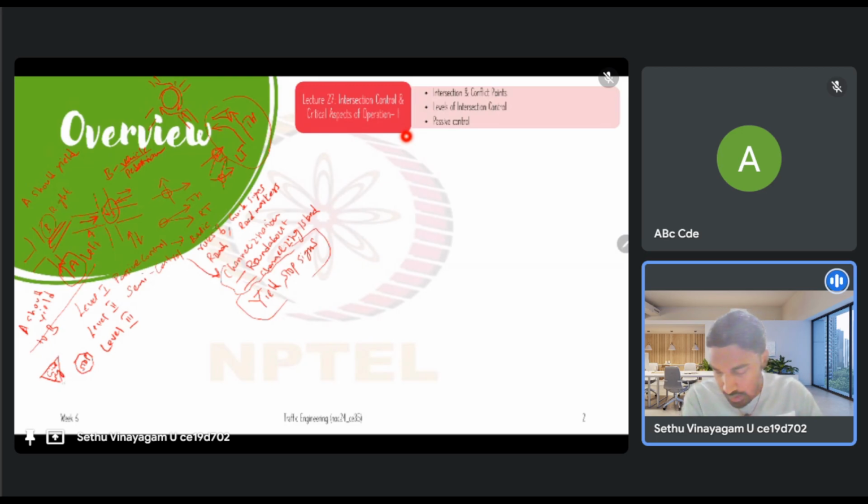So what is the difference between the yield sign and the stop sign? A yield sign means the vehicles coming towards the intersection have to slow down, and if the condition is not safe, they have to come to a complete stop, and when a safe gap is available, cross through. But once they slow down, if they have enough gap available, they can pass through without stopping as well.